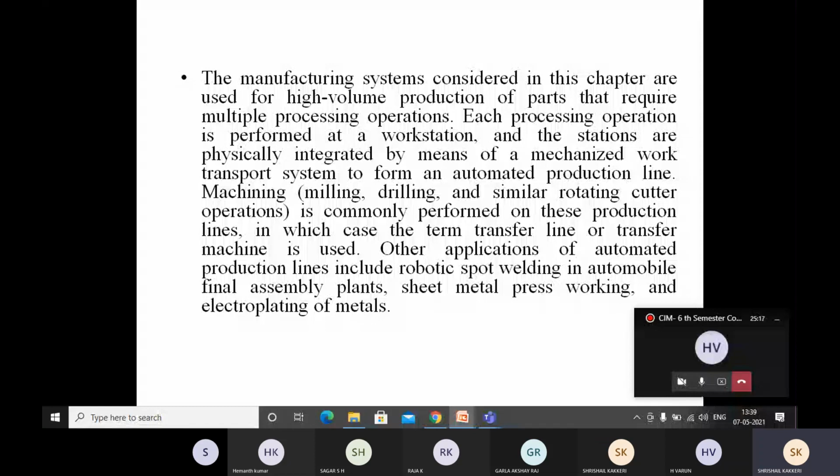Now please remember here, A machine, B machine, C machine. The A workstation, B workstation and C workstation may not have the same cycle time. As I already told, the cycle time consists of the non-operation time, operation time, work holding and handling time, and maintenance, everything included to complete one cycle. So definitely the threading and the plain turning will not take the same amount of time.